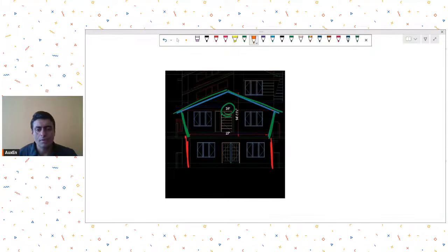So, I mean, there will be no basic difference in the analysis. You may have to model it like this, and then for this pitch roof, you calculate all the wind loads, etc. Everything. For these slanted columns, you calculate the wind loads. They may not be very different from your condition if you had a straight column. So even for a slanted column, your wind load coefficients will be the same. Now when you apply the loads, you just need to check that because of this slant, there will be additional moments created. So those you have to take into account.